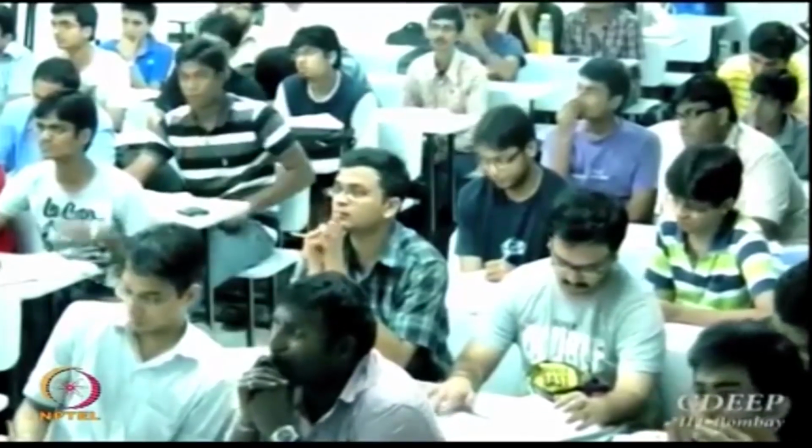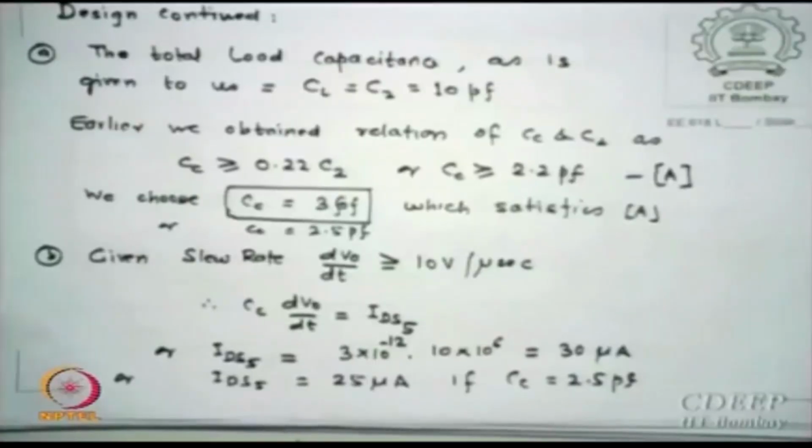Sir, is this slew rate of the op-amp or the gain stage? Because it is not the op-amp, it is essentially V0 going at the CC output. So the output rises as the capacitor CC charges. Sir, there is a capacitance C2 also. But that is not actually charged by this current, it is charged by M6 or M5.